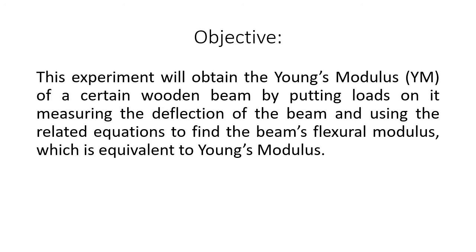This experiment's objective is to obtain the Young's modulus of a certain wooden beam by putting loads on it, measuring the deflection of the beam, and using the related equations to find the beam's flexural modulus, which is equivalent to Young's modulus in this case.